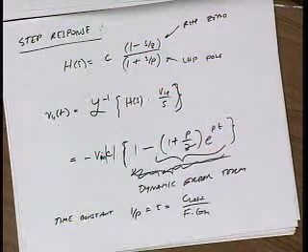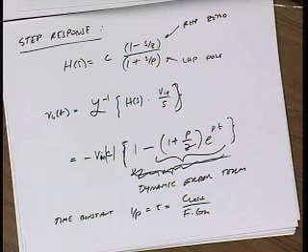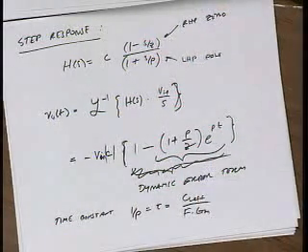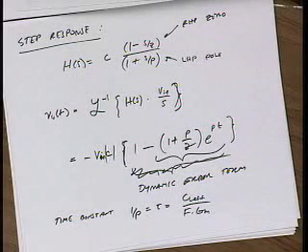Okay, Debo, you want to use a mic? You can consider the non-dominant poles still. Let's forget those for now, right? Okay, that's fine. If you consider non-dominant poles, then the bandwidth will be set by your non-dominant pole, which is on the order of ft, which is really fast. So okay, I don't get infinite bandwidth, but I get, let's say, 10 gigahertz, 20 gigahertz. Is that physical?